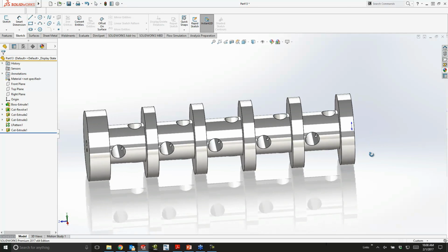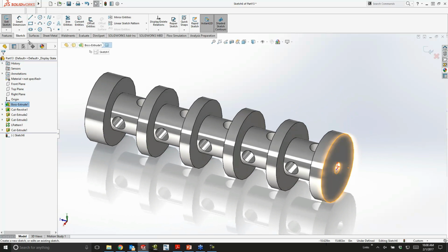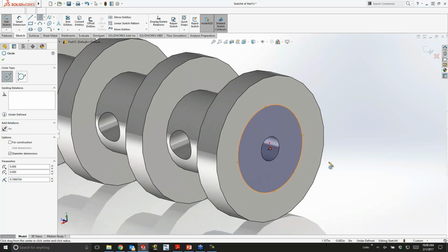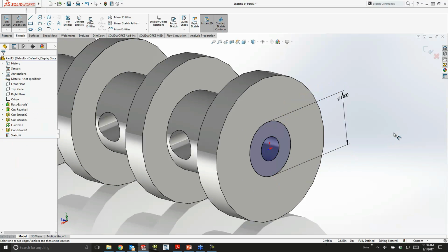As we keep going along, this thing needs to be mounted on the gun. So there's going to be a boss down here where we're going to need to thread it. And so I'll go ahead and convert the ID, create the dimension for the OD, and we'll just set the size that we want to do for that threaded feature.